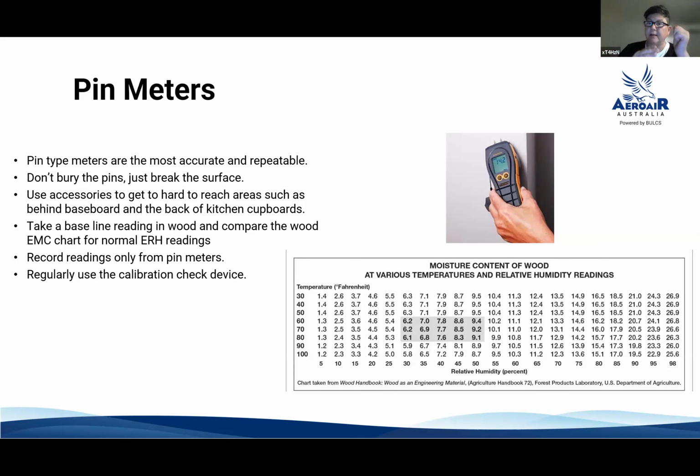If it goes under 9%, the kiln drying is when the wood is cut from the trees. They have to go into a kiln. They dry it so they can stabilize that material to a certain point, and that point will always be around 10% moisture content. That's why the Australian standard is between 9 to 14%. If it's in Queensland, it's 9 to 15%, just around that.